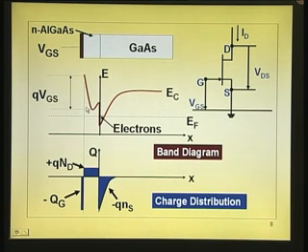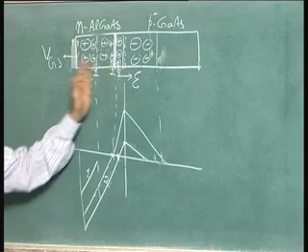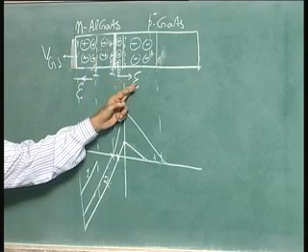So, wherever the potential is positive, conduction band goes down. So, it is plus here with respect to that point. That is why the energy band diagram is dipping down. Minimum potential, this is the situation that is shown there. Minimum potential corresponding to 0 field, and from there to left hand side, field is from right to left, from here it is left to right.